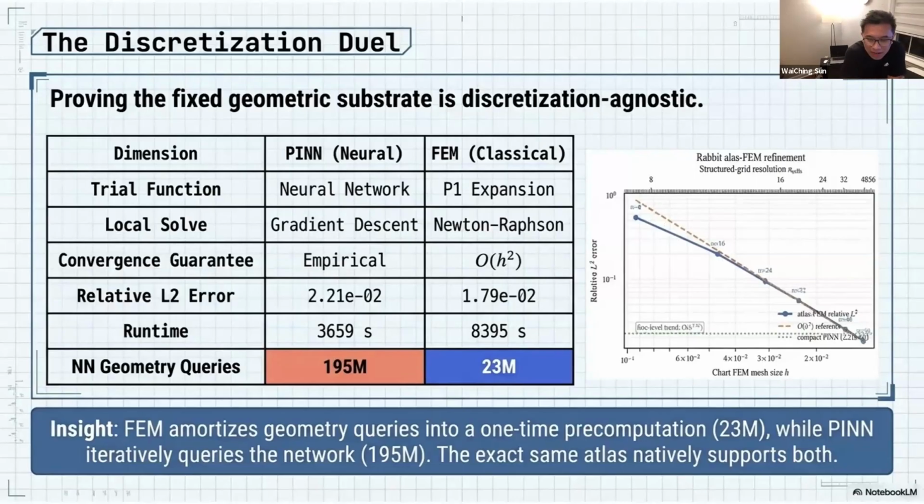There is one downside for that method, though. Compared to the classical finite element, how dense the tangent matrix is would depend on the mapping. If there's a lot of shear or distortion, you would expect the Jacobian to have a lot of off-diagonal terms, and hence the resultant tangent would not be as sparse.